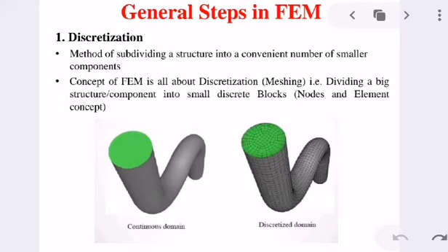Discretization is an essential step to help finite element method solve the governing differential equation by approximating the solution within each finite element. The process is purely based on geometry of the component and usually does not require the knowledge of differential equation for which the solution is sought. The accuracy of FEM solution depends on the fineness of discretization.